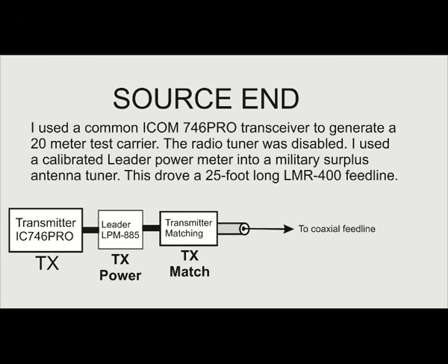So that's what that percentage is. That's why it shows up on a VNA or a network analyzer, and that's why it will not show up when we test a piece of cable and we use a matching network at the transmitter end to correct the mismatch in impedance presented by the coaxial cable to the transmitter.